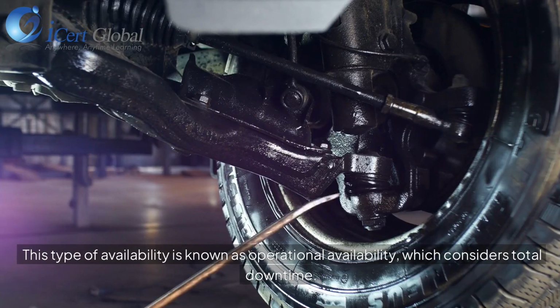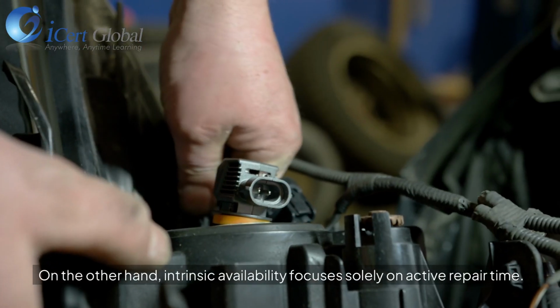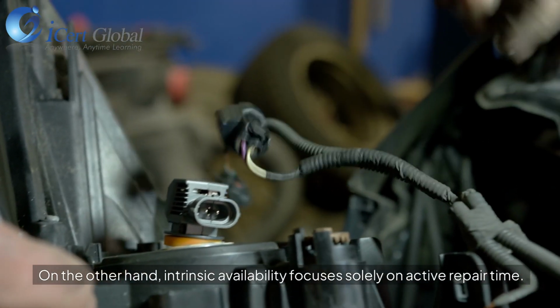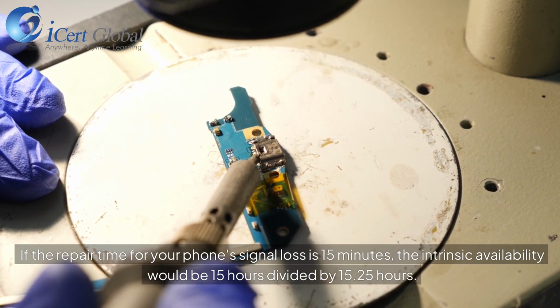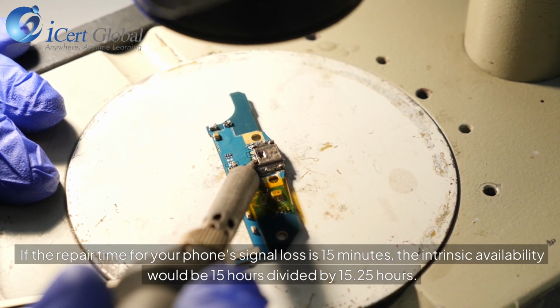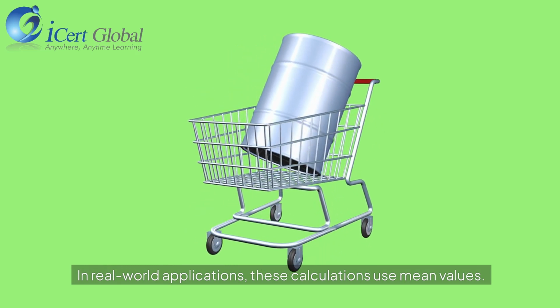This type of availability is known as operational availability, which considers total downtime. On the other hand, intrinsic availability focuses solely on active repair time. If the repair time for your phone's signal loss is 15 minutes, the intrinsic availability would be 15 hours divided by 15.25 hours. In real-world applications, these calculations use mean values.